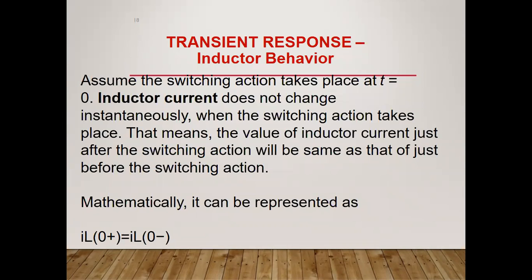Similarly, the value of the inductor current just after the switching action will be the same as just before the switching action. The meaning here is very important. When t is equal to 0, small t equals 0, there are two cases: small t equals 0 minus is one case, and small t equals 0 plus is the other case.